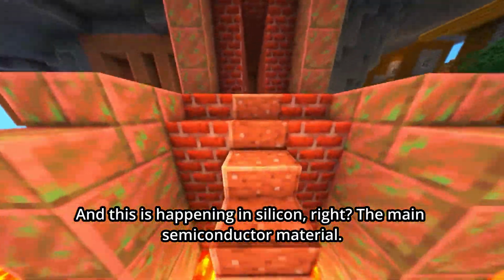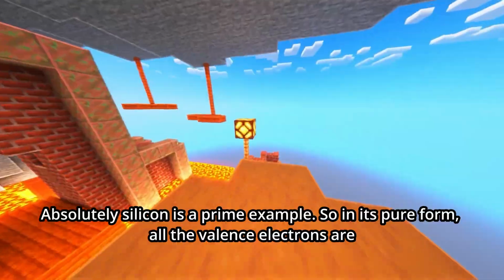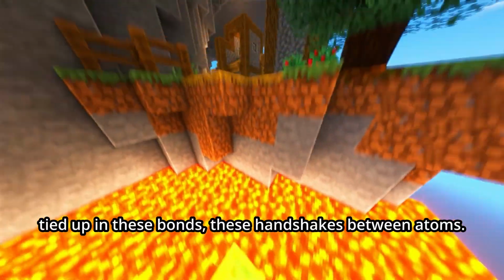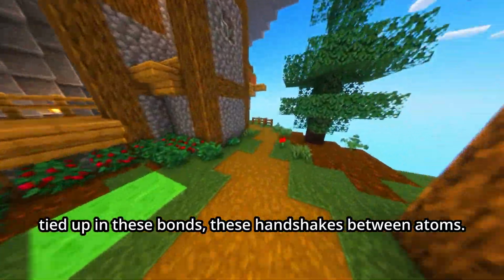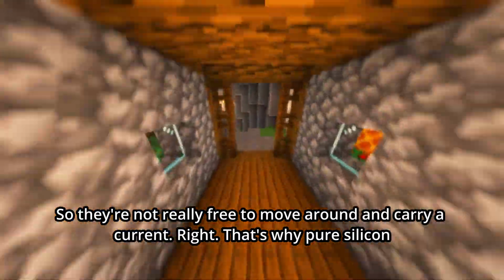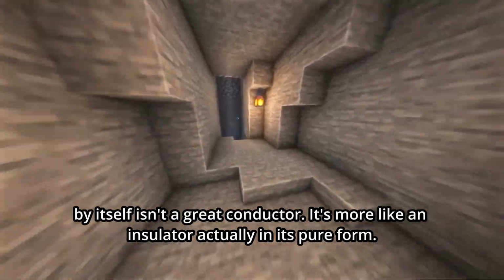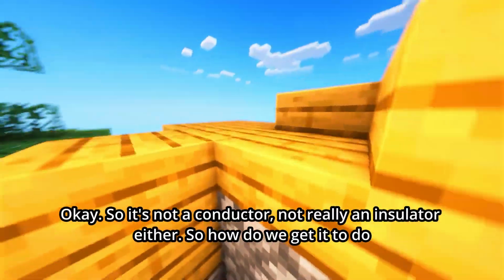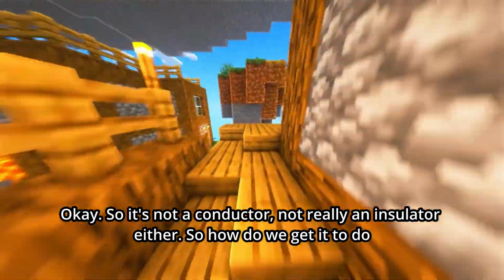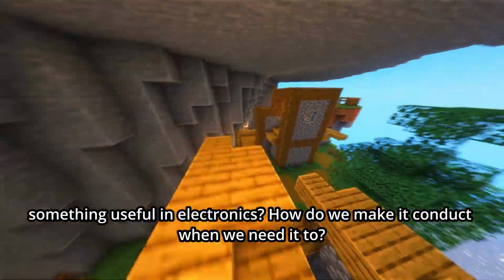And this is happening in silicon, right? The main semiconductor material. Absolutely. Silicon is a prime example. So in its pure form, all the valence electrons are tied up in these bonds, these handshakes between atoms. So they're not really free to move around and carry a current. Right. That's why pure silicon by itself isn't a great conductor. It's more like an insulator, actually, in its pure form. Okay, so it's not a conductor, not really an insulator either. So how do we get it to do something useful in electronics? How do we make it conduct when we need it to?